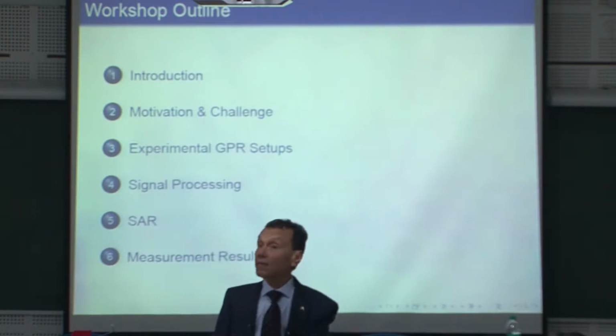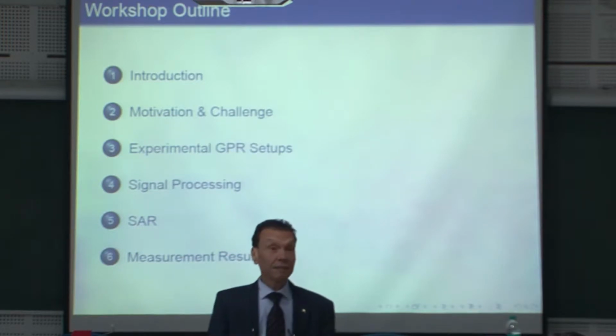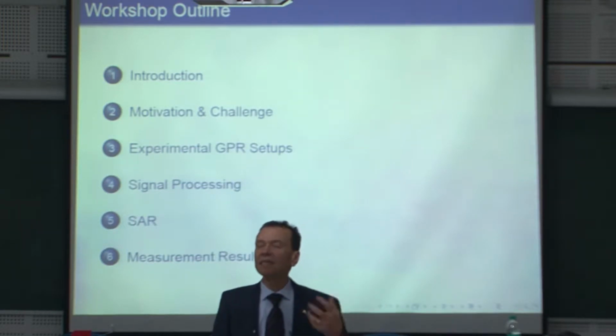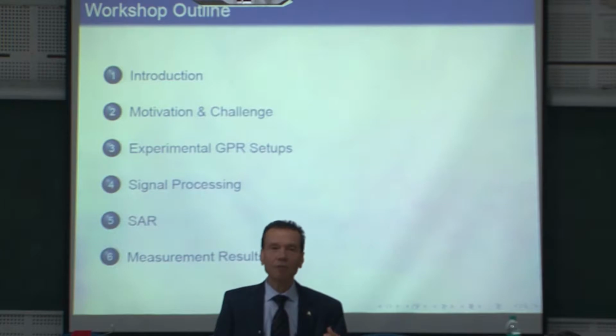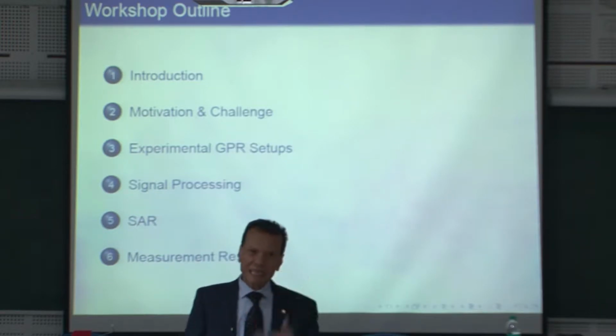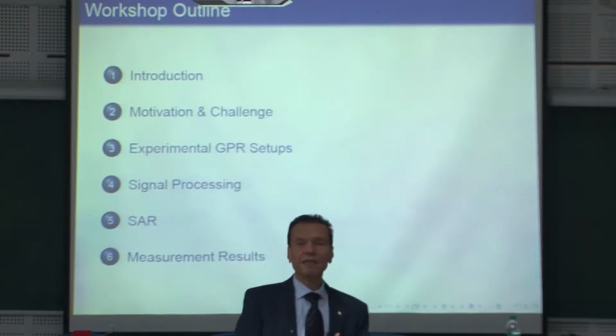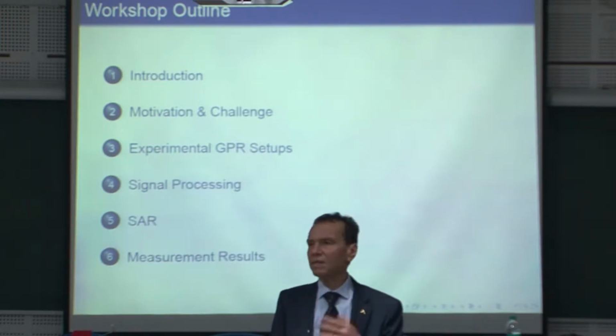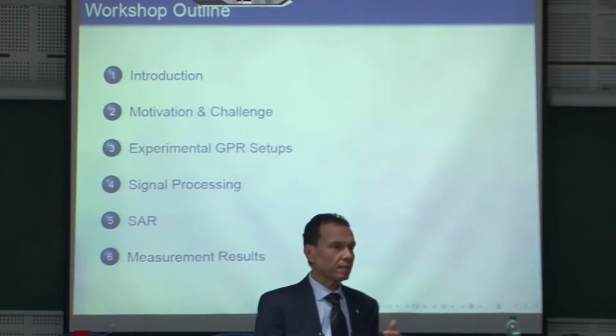What you know in digital signal processing as aliasing, in antenna arrays is defined as grating lobes, where you repeat yourself many times. Okay, but whether we have discrete point antennas or continuous, more or less we are the same. The continuous is something like analog signals. The discrete is digital signal processing.